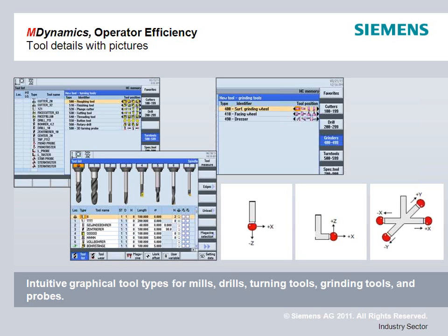One of the screens that we're going to talk about later, you can just say that we'll make this counterbore and the control will do the calculation for you. So if you're going to be doing things at the machine where you can take advantage of that, it's worth setting up and punching in the numbers correctly. In a lot of aerospace shops, they tend to skip this step because the data is coming in from somewhere else. You don't want the operator touching these screens. If you don't define the tools correctly, the machine's still functional. But when you start getting into the programming of the machine functions, this does save quite a bit of time for your operator.